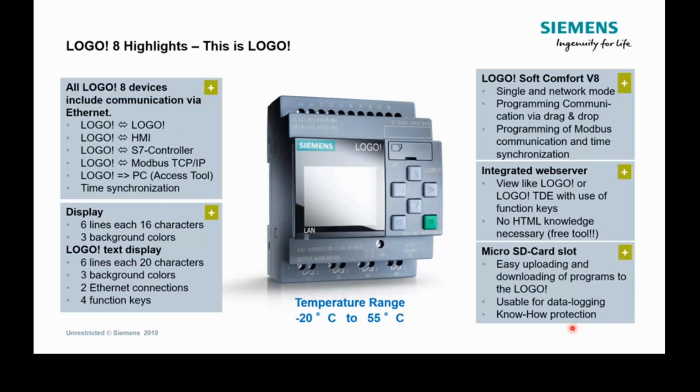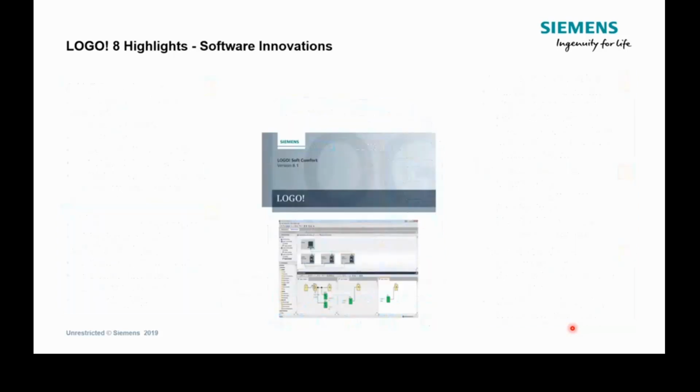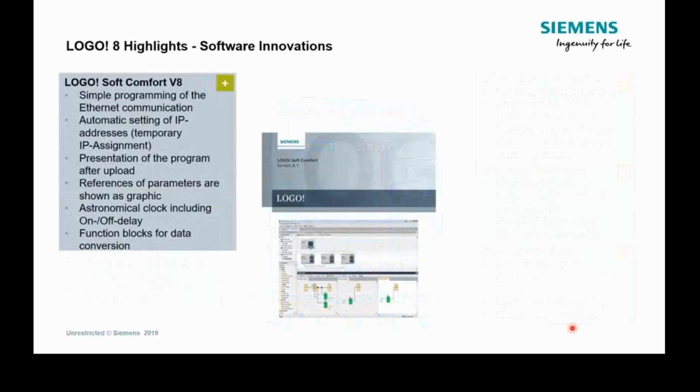You can see there the temperature range, -20 to +55, so a really wide applicative area for temperature there. Maybe in the sort of freezer and refrigeration environments, we can start to think about mounting controls in different areas to save us a bit of money, maybe on running cables long distances and things like that, and all the way up to +55.